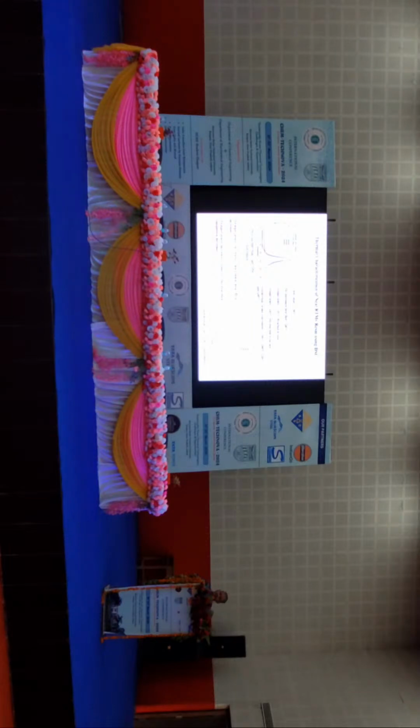So this is for another resin. This is the RTM6 resin, which is applied in the aerospace industry. Whatever procedure I dealt with has been followed for this resin also. So you can see the non-isothermal cure DSC experiment and the isothermal cure DSC experiment.